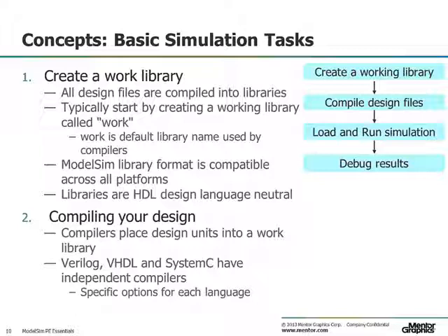So the first step is creating a work library. All design files are compiled into libraries. Typically, you start by creating a work library called Work. It's the default name. The ModelSim library is compatible across all platforms and also across releases. And they're HDL design language neutral. So in one work library, you can have Verilog, System Verilog, VHDL, or System C. That's a work library. And this is also part of the advanced topic where we talk about managing more complex environments, generally associated with multiple work libraries.